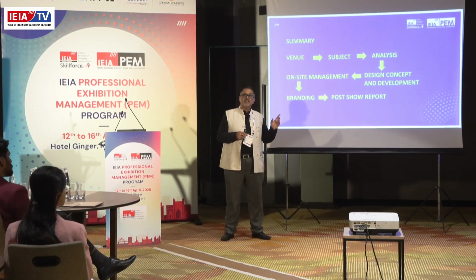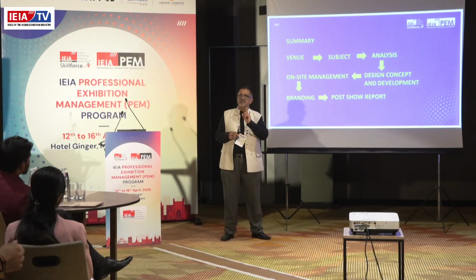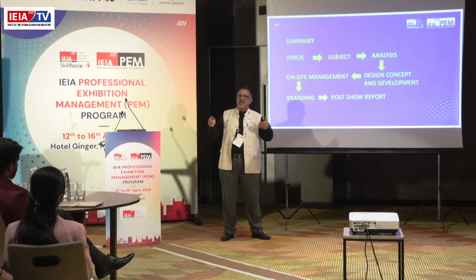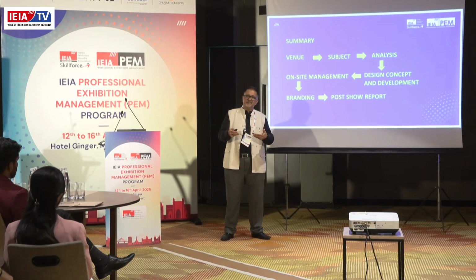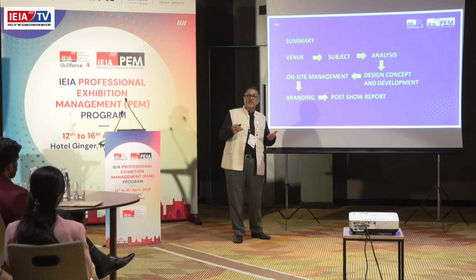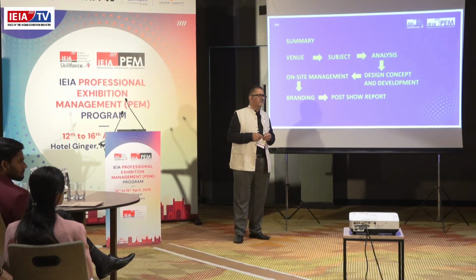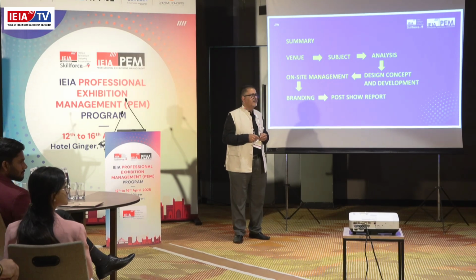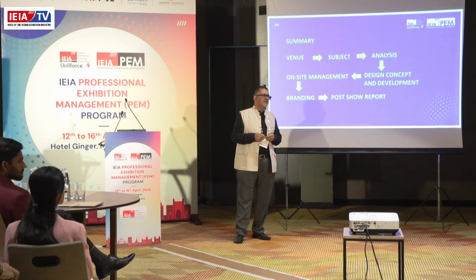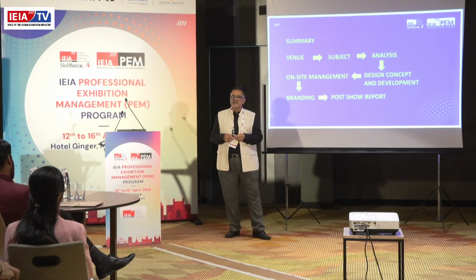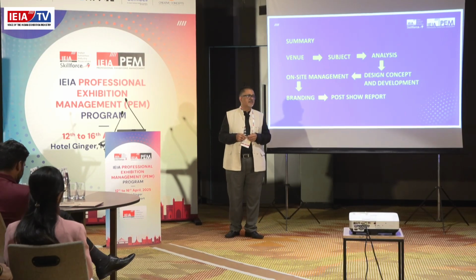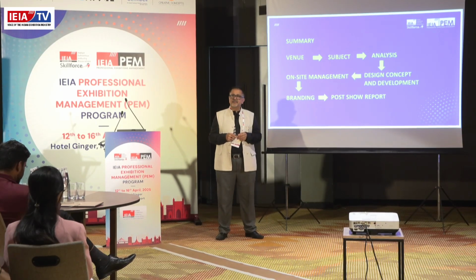That's why these days we have a toe wall all around the structure, so that in case it is raining, the water doesn't seep in. All these are very important points to be considered when creating a temporary structure, as you rightly mentioned. And temporary toilets. In a temporary structure, you cannot live without good quality toilets.